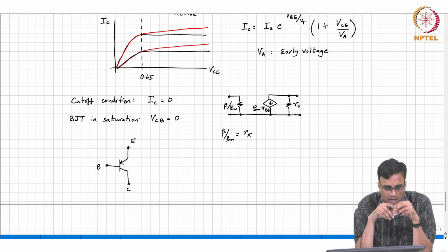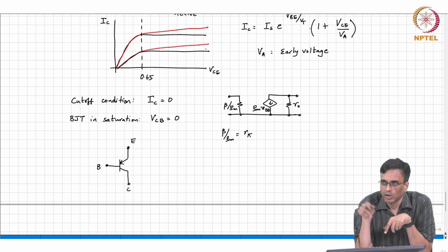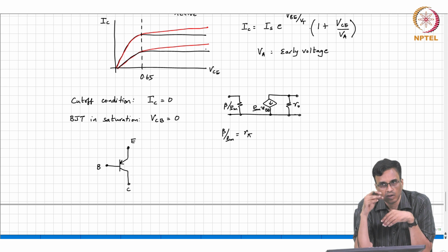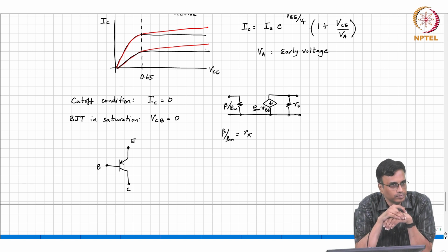And we do not like currents flowing from the bottom of the page to the top of the page. So, rather than turn the page or turn your head, you draw the emitters of the PNP transistors on the top, and then the current flows downward.